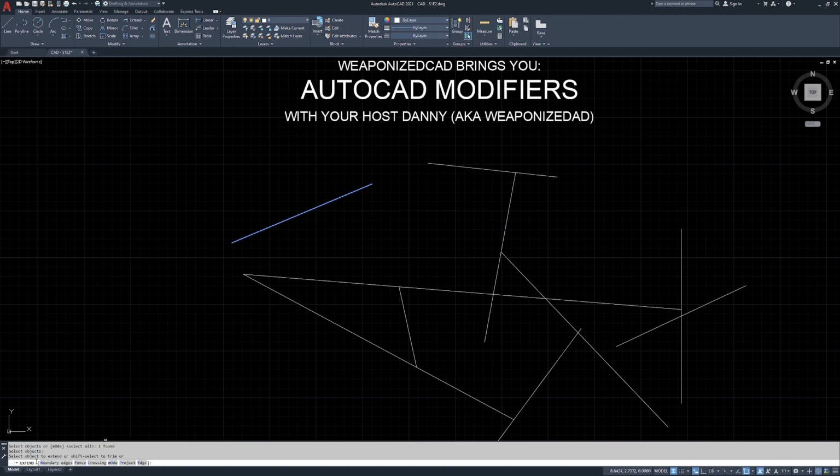So down here in the command line, you're going to notice that you get this edge button. Click the edge button and set it to extend, because it's going to give us an implied edge. So even though these two lines don't intersect and will not intersect when this is extended up to here, the implied edge tells AutoCAD, ghost this line out a little bit further and give this line something to hit. So we're going to set that to extend.